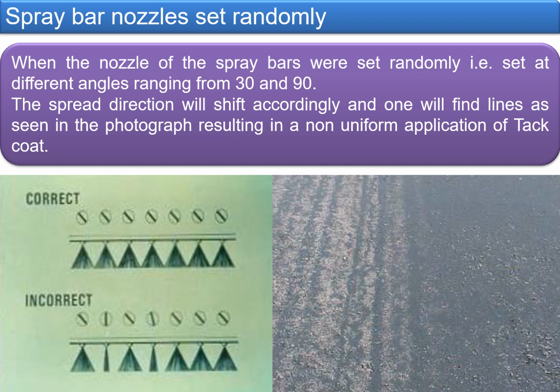So to avoid these types of applications, you must ensure that the nozzle is at an angle of 15 to 30 degrees, and all the nozzles should be at the same angle of opening with respect to the axis of the spray bar.